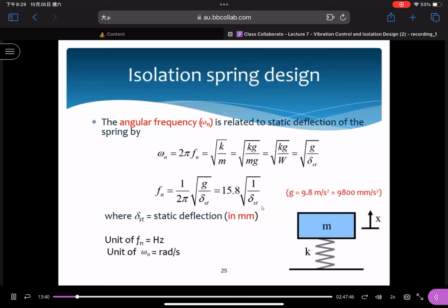When you refer to the over damping case and critical damping case, you can see that no oscillations occur. Okay, when we release the system, the system will go to zero without any oscillations about its equilibrium position. Only the last one, when zeta is less than 1, when the damping ratio is less than 1.